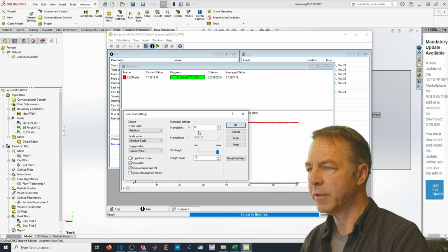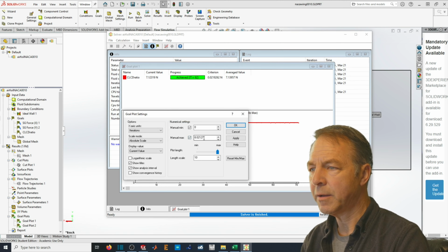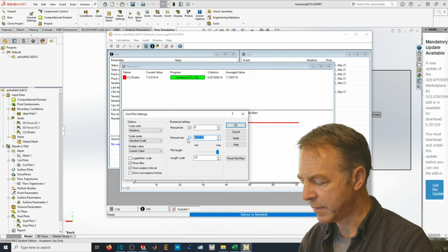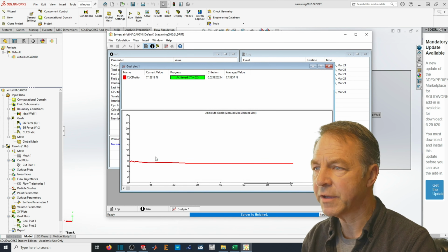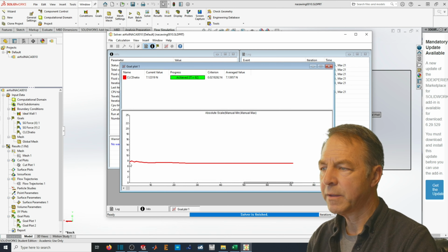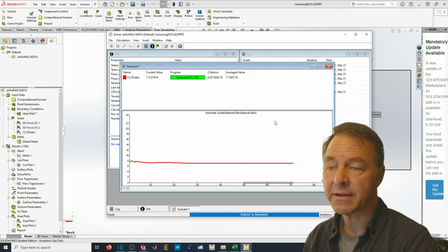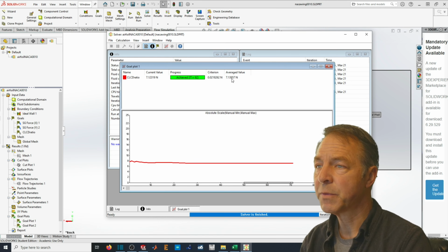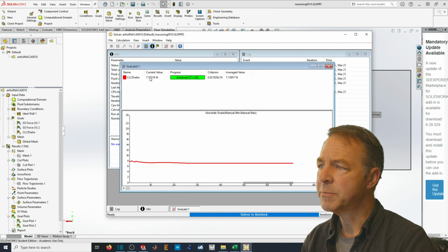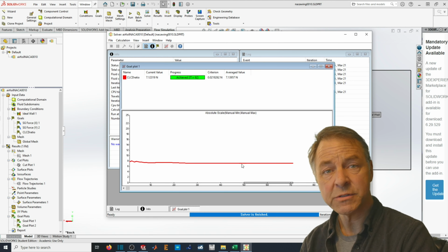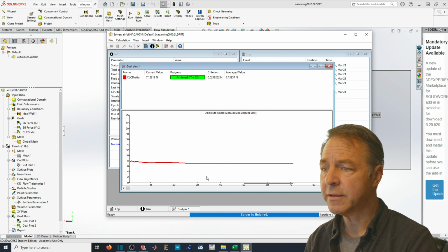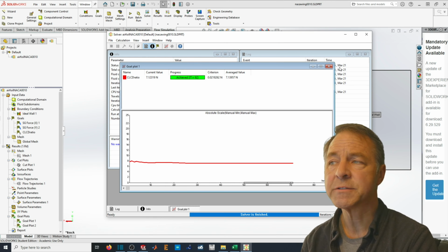And because we know that this is going to be a scale that we want that should be 22, I'm going to pick 25 there. So it oscillated and it did stabilize after 70 odd iterations. It came out at 7.1 newtons, which is different than our first run at just simply changing the grid size.